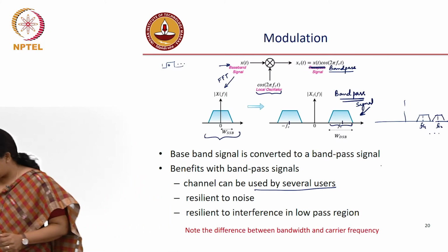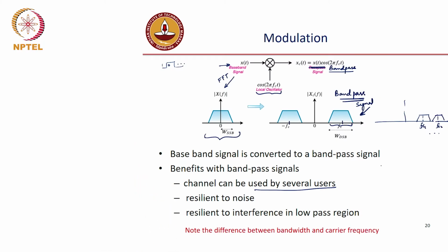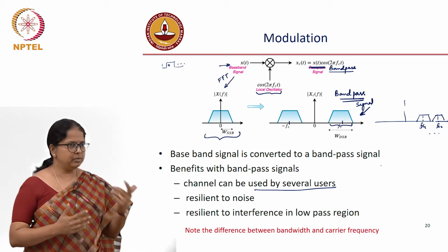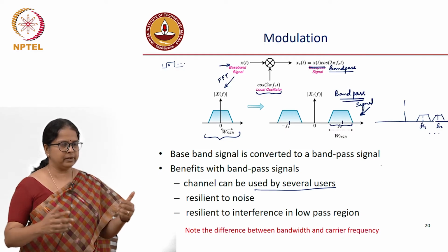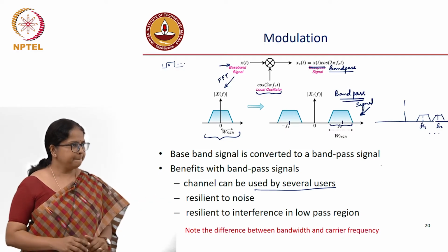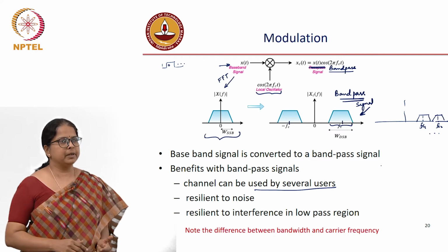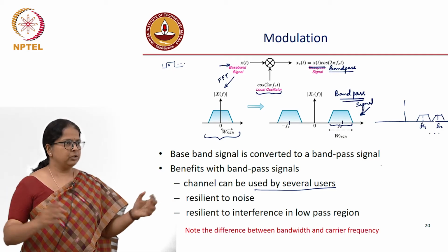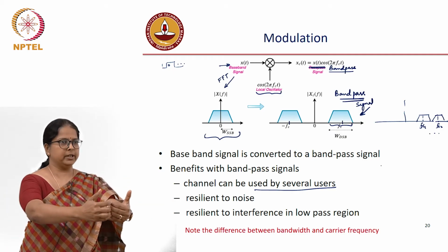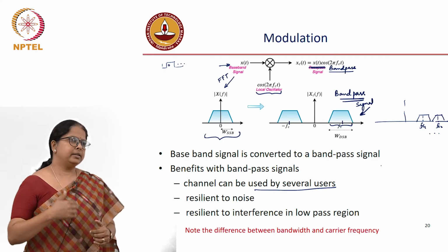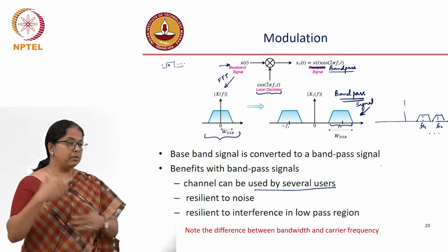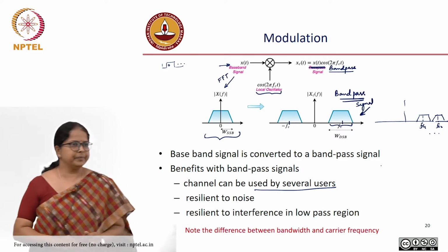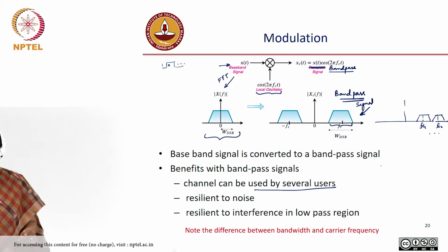Alright, so we start from the point where we stopped earlier. We discussed why we need modulation. We need modulation so that we can use the channel very effectively. We need modulation because there is a constraint on the physical layer that you cannot make very big antennas. You need to shift the frequency of operation to higher frequencies, and at higher frequencies, the power required for radiation also has an implication, but let us not get into those physical layer implications.